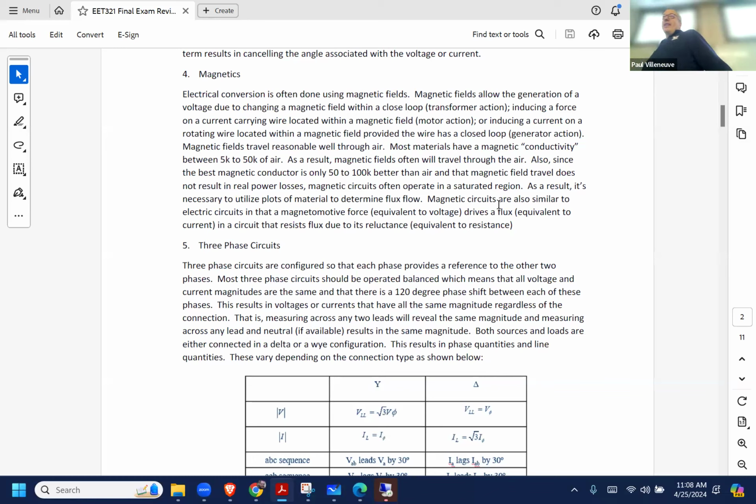We also use magnetics for transformers, and transformers have electrical isolation between the primary and the secondary, unless they're connected. I actually reviewed a circuit for somebody over at the structures lab that had a 480 to 208 volt transformer, and the 480 was delta connected and the 208 side was Y connected. He showed the neutral all connected to the same point, but he didn't show a ground.